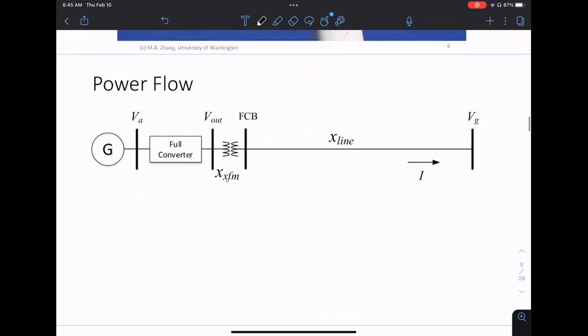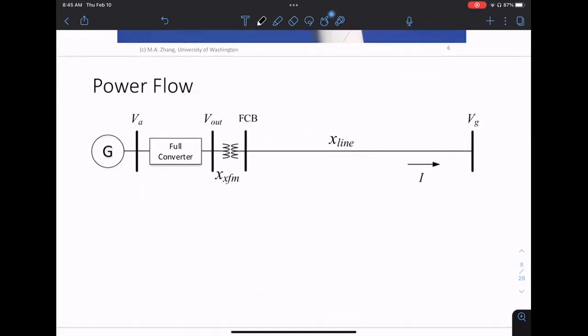Okay. So now we can look at power flow. We'll do some calculations. Again, the equations will come out simpler. The equations for synchronous machines are much simpler than for induction machines, because you are setting the frequency. So you don't need to compute the slip. There's no slip business. As you're directly setting the voltage, it makes all the calculations easier.